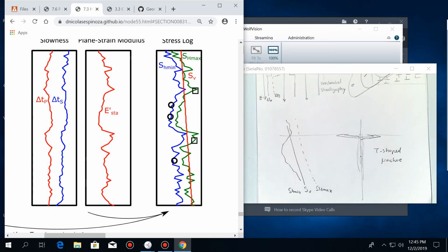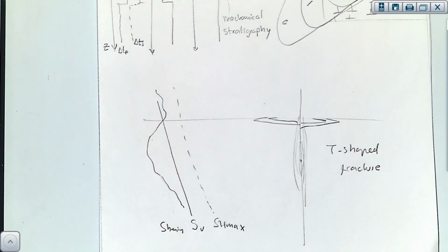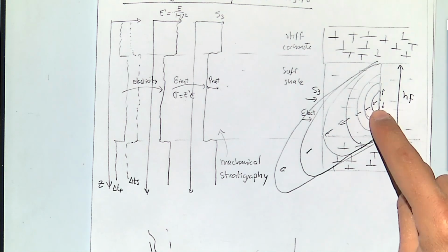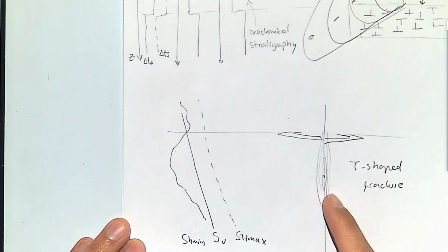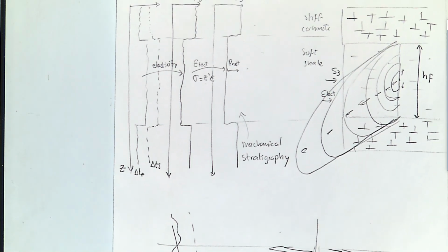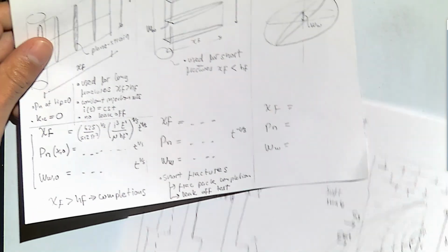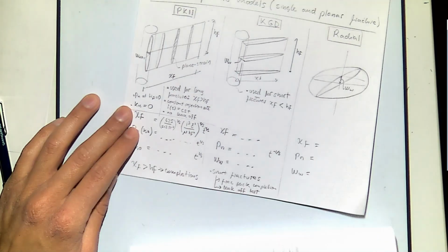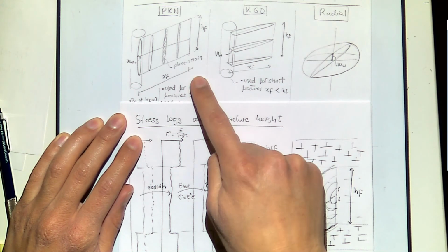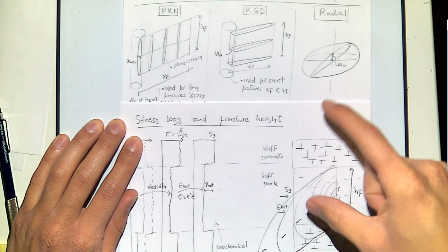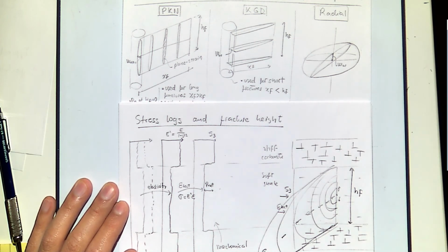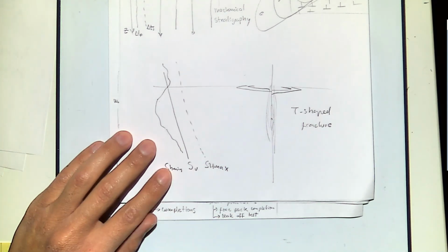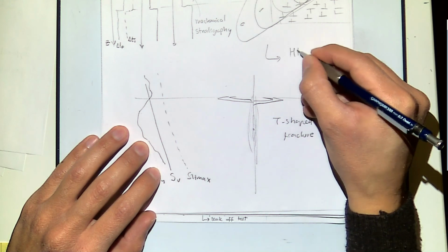All right, so now if you put together these concepts of hydraulic fracture height, this is a simple one, but now if you consider the effect of the net pressure and when it will continue growing or not, or if it will turn or not, and you add this together with the equations that we have seen and with the models that predict net pressure and fracture length, and all of that together with something in which you do not set the hydraulic fracture height, but you calculate it as you go, that's everything that you need in order to make a hydraulic fracture simulator.